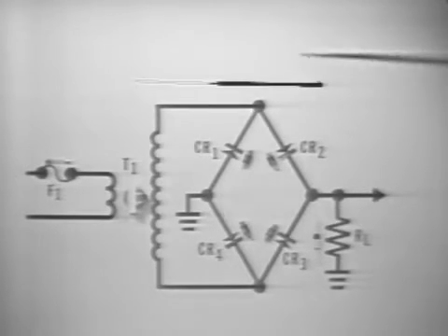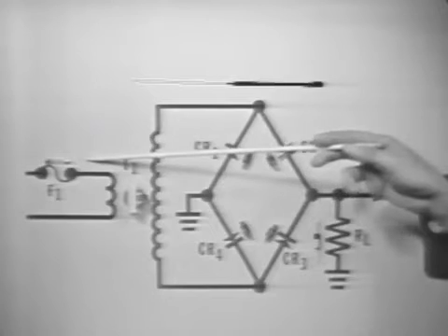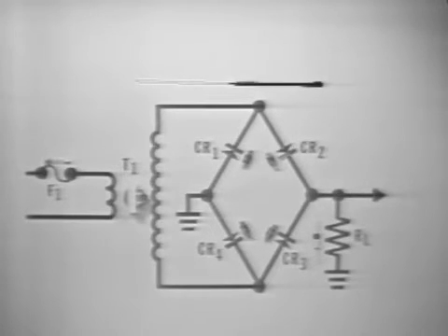Notice that all of the output is gone. Our symptom of malfunction then is no output. Now, what could cause this problem? Well, the first thing to check, of course, is the fuse. If it's blown, you will have no output. But let's assume for now that the fuse is good. So what else do we check?